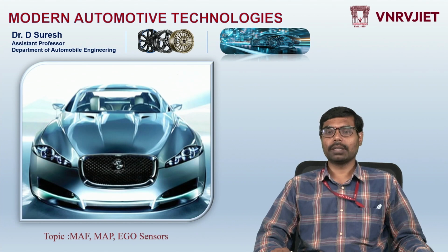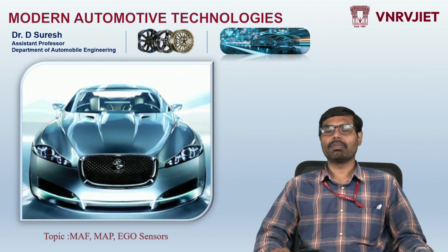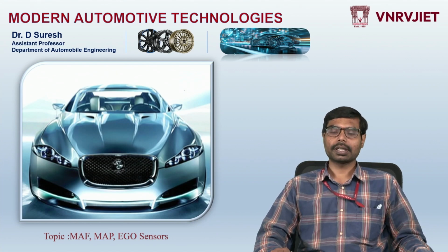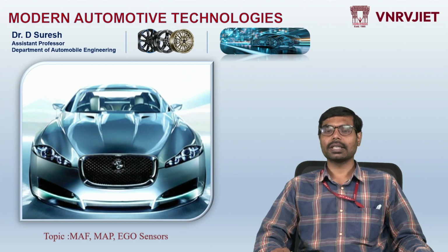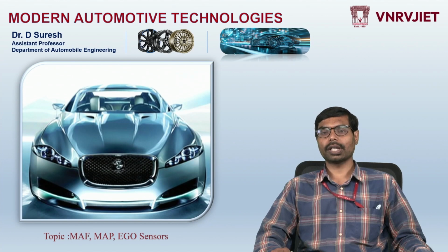as we mentioned in the previous session also, are the throttle position sensor, manifold air pressure sensor, mass airflow rate sensor, exhaust gas oxygen sensor, TDC signal and cam position signals, engine RPM sensor, engine speed sensors, and engine coolant temperature sensor. So like that we get different sensor inputs. Based on that, the ECU will analyze for the best possibility of getting optimum fuel output for injecting into the engine to maintain the stoichiometric air fuel ratio of 14.7 to 1.